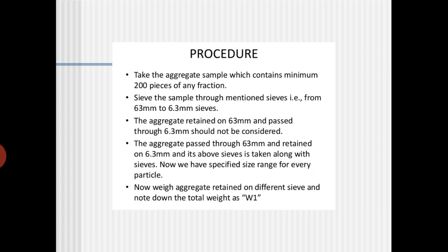Of course, wherever the subbase layer or subgrade layer is weak, in those cases you have to add a greater size of the aggregates so that it is strengthened, and the CBR value should be increased to about 20. Then above that you can use different gradations of the size and compact it.